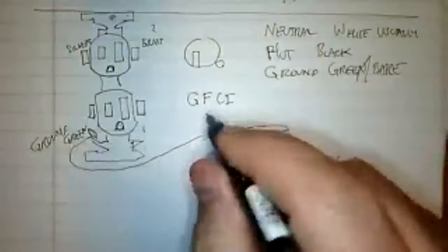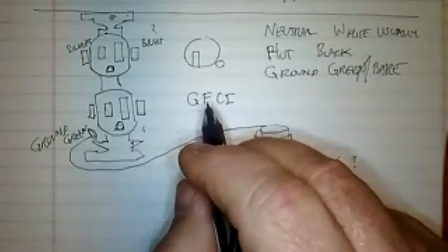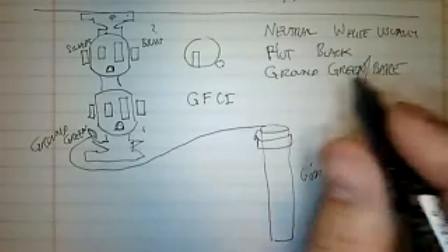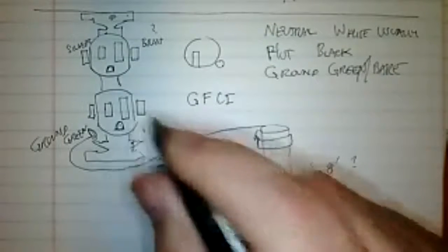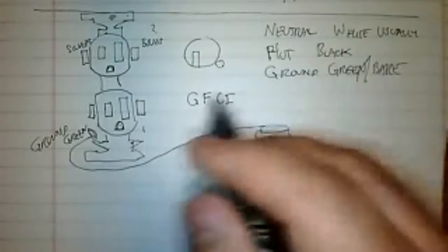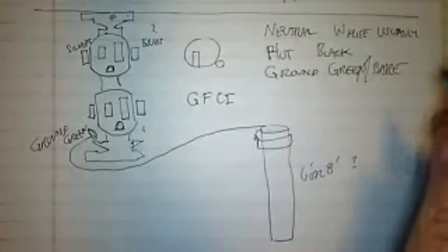Which it's supposed to, right? And if you're in an old house, they don't have GFCIs, and they don't have to put them in until they do an amount of work that's comparable to the value of the home. It would be good if you're renting a place to put them in yourself, if you can. But like I said, it's a really good thing to have, these GFCIs, and that's what they do to save you from, you know, dying.